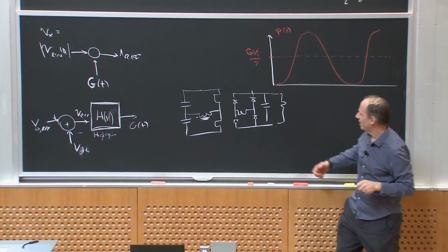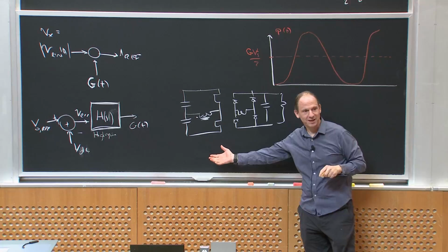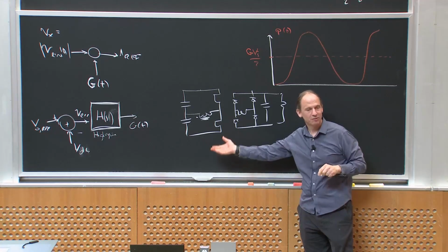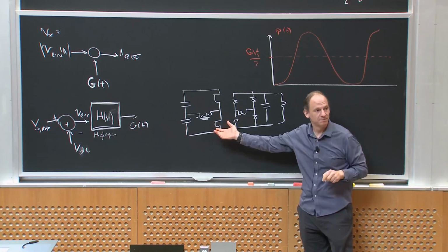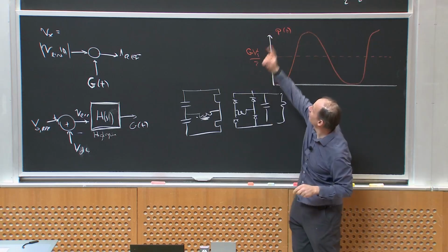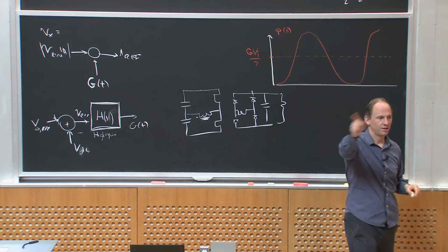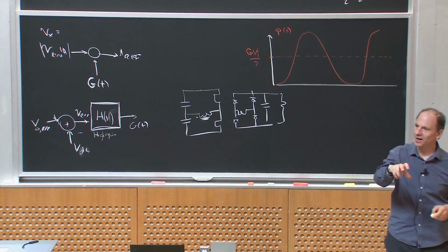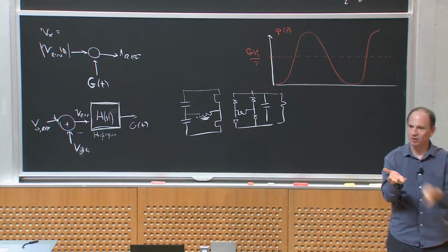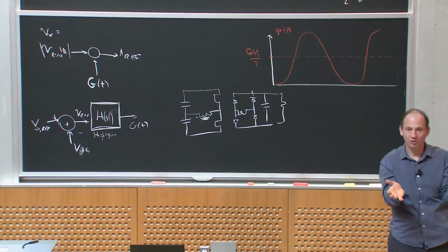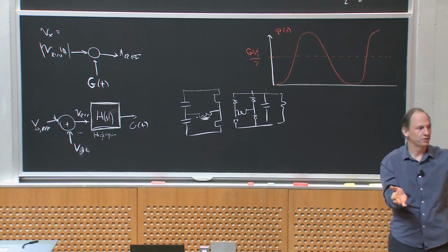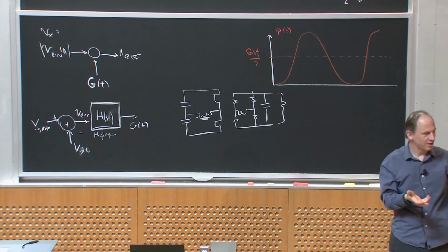Or maybe I have multiple outputs from the next stage, to give plus and minus 12 and plus 5, whatever I need, okay? But I will usually have some subsequent stage, and in fact, the other board I'm passing around is the subsequent stages to provide from the high voltage rectifier down to lower voltage loads, okay?